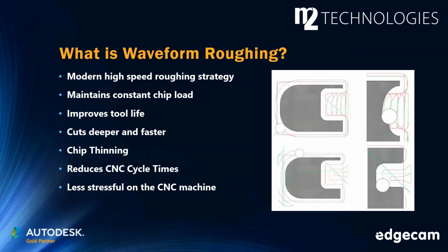One is that tool life is improved. We can often cut much deeper and faster than traditional cutting techniques. And with things like the chip thinning effect of the cutting path, we're able to achieve higher overall feed rates without stalling the tool or creating more cutting pressures on it.